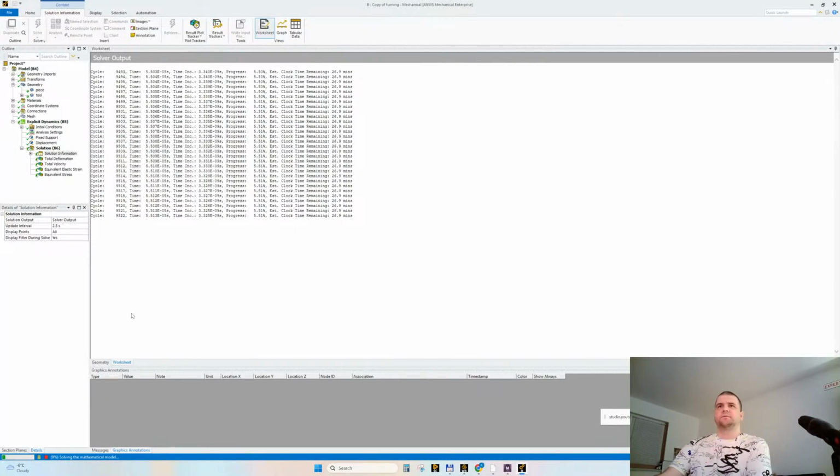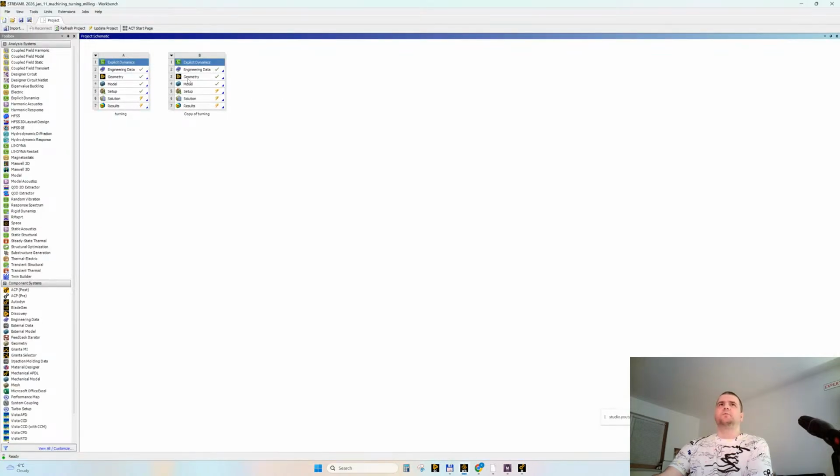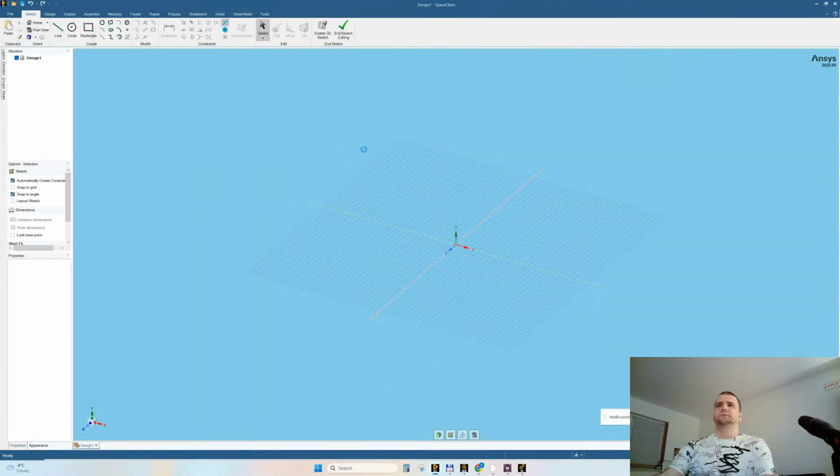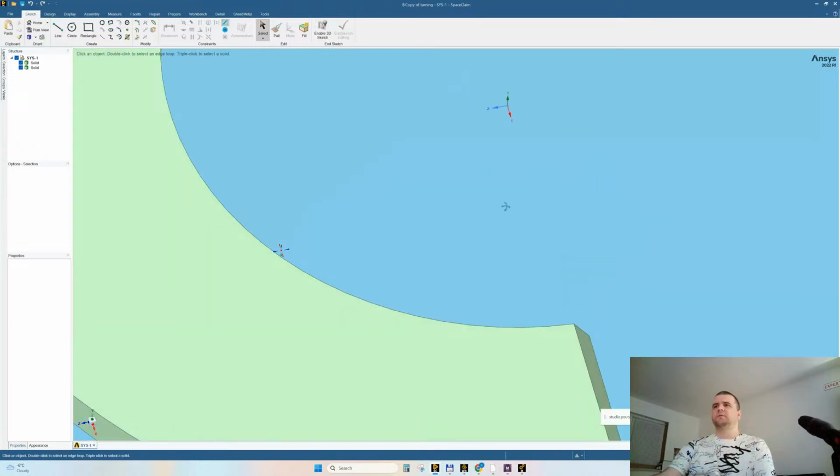26 minutes, 27, half an hour. Yeah, let's try and make it even faster. One proposal would be to make the annular portion, the annular ring, or the initial tube, even thinner in order to save some meshing, to have fewer nodes. I was talking about this.